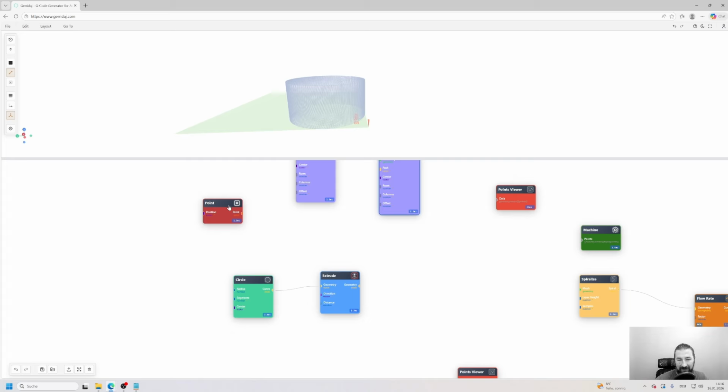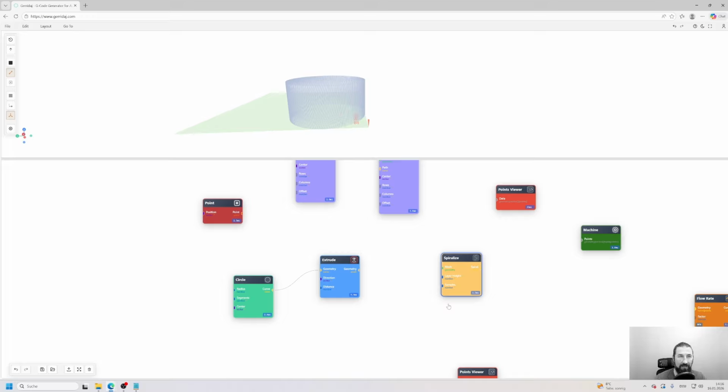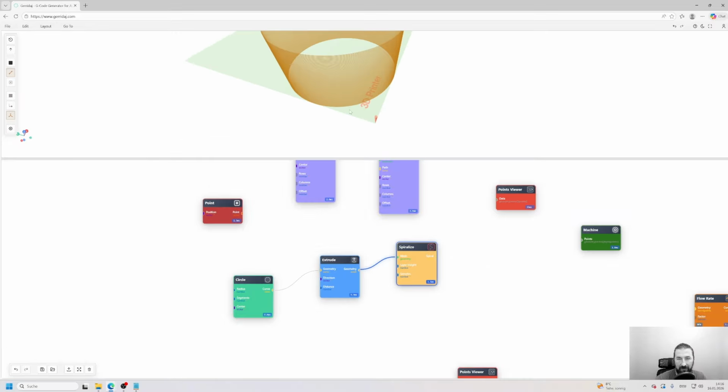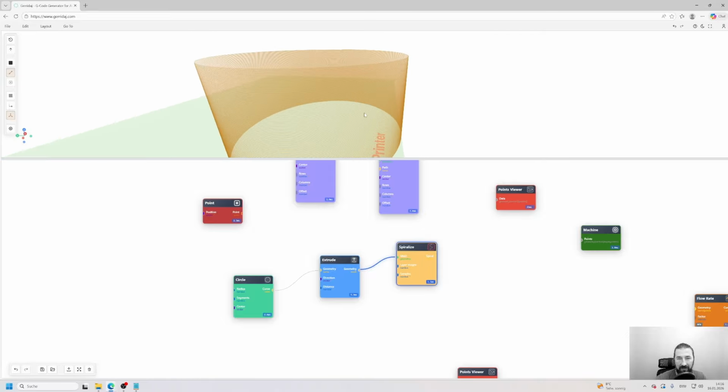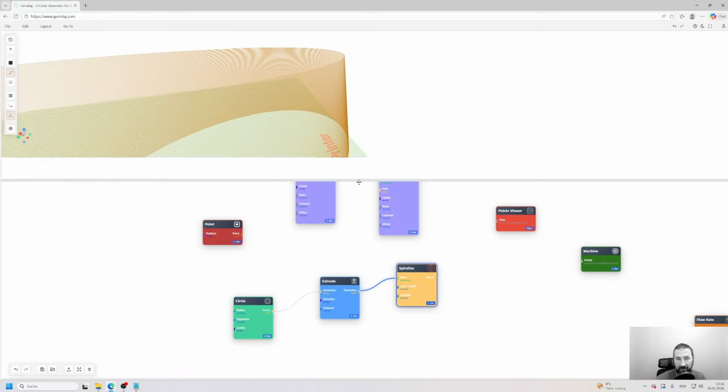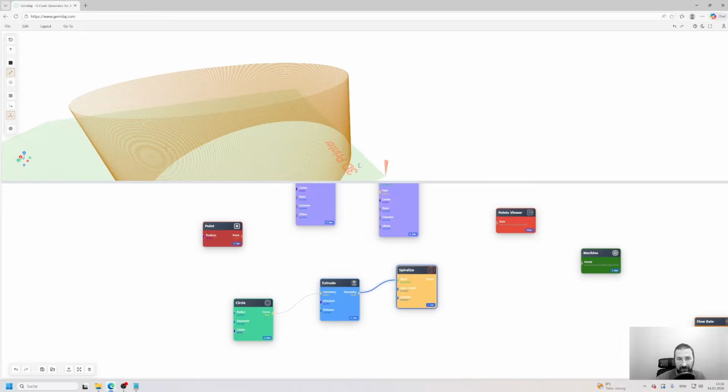So here we have seen how to design from the points first, and here you see how you create a mesh first and then you get points. This is what slicers also do, but we will do it in a little bit different way. Because we're normally interested in, let's say, artistic cases of lamps and lampshades and vases, you actually need normally only the outside vase mode path and not the inner parts of the shape. And then you can just use spiralize mode, which gives you a similar path to what you will get from vase mode in a normal slicer. But you don't need to switch to another software, you can do everything here.